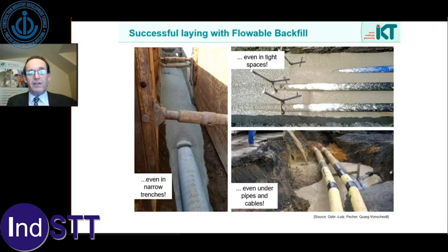So what it might look like at the end of the day: poured into a narrow trench, filling around the pipe, getting into small tight spaces between different utilities, and working quite well in odd shapes where it might be otherwise very difficult to get in and do your normal compaction.